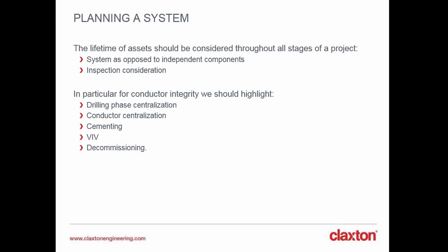The design will then need to consider these aspects, but make sure not to neglect the inspection phase or phases of the equipment as well, because that's another area of potential problems. It's not uncommon for structural elements to be fitted in a way that makes access for inspections unnecessarily impractical. So something might be fitted in a position where you cannot get access unless you first remove another structural element before you can actually reach the equipment.